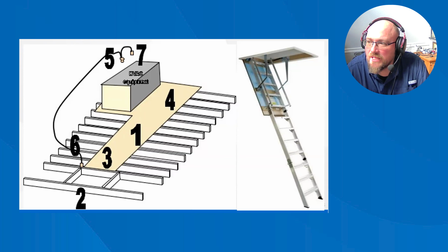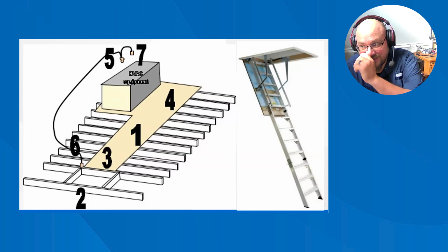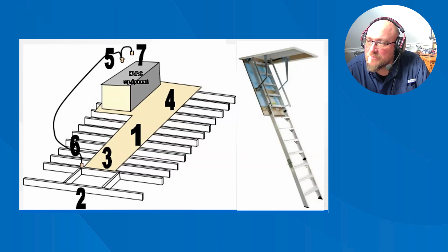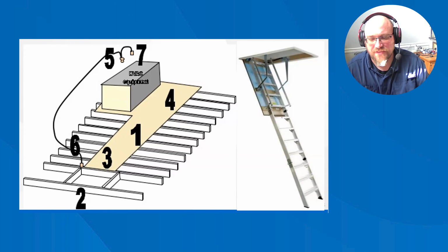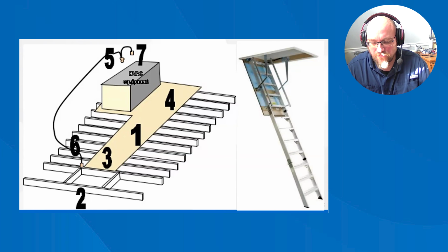Loose mounting bolts. This condition is more often caused by age rather than a defective installation, although improper installation will hasten the loosening process. Attic pull-down ladders that are cut too short or cut too long, and attic feet that are not cut to the slope of the attic floor. When the bottom of the stair rail is just hitting on that bottom corner, that causes the ladder to be very unstable and wobbly.